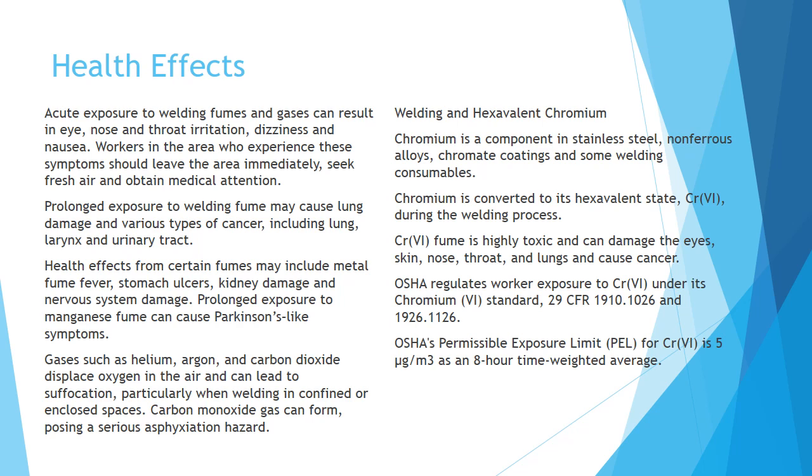Health effects. Acute exposure to welding fumes and gases can result in eye, nose, and throat irritation, dizziness, and nausea. Workers in the area who experience these symptoms should leave the area immediately, seek fresh air, and obtain medical attention. Prolonged exposure to welding fumes may cause lung damage and various types of cancer, including lung, larynx, and urinary tract. Health effects from certain fumes may include metal fume fever, stomach ulcers, kidney damage, and nervous system damage.